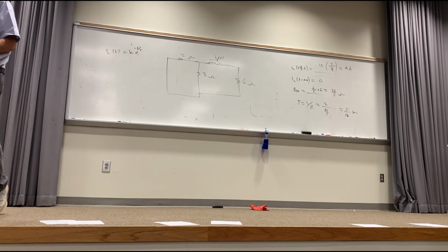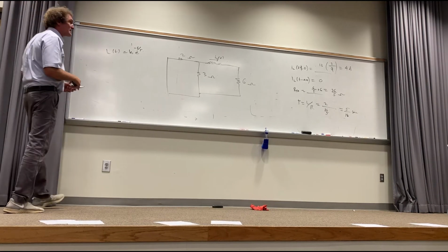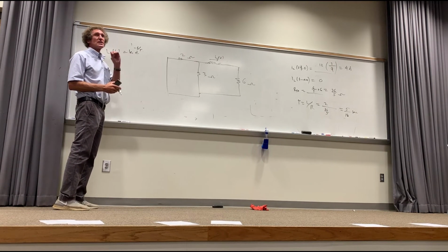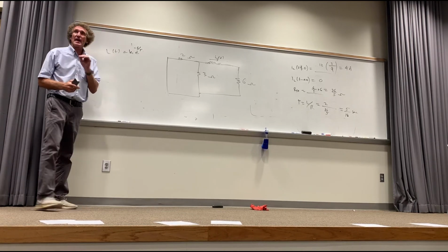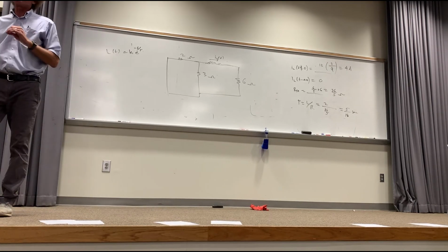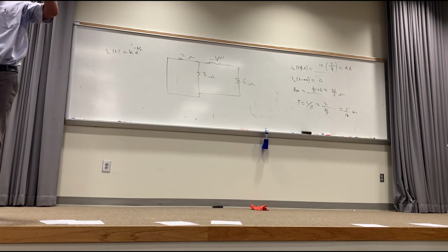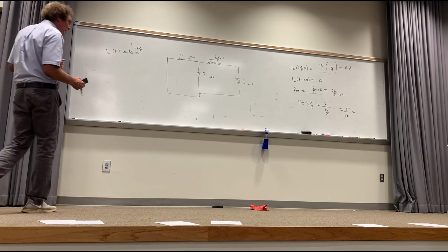Now the next thing. I need to find out what K1 is, right? So I evaluate the current at t less than or equal to 0. And by the way, current through an inductor cannot change instantaneously. It can't go from 0 to 50 amps, or it would imply an infinite voltage. There has to be a continuum. There can't be a discontinuity. So based on that, the current for t less than 0 is the current for t greater than 0.